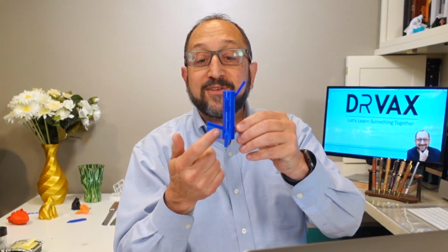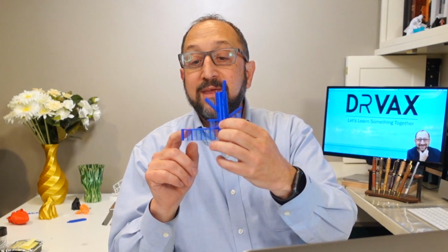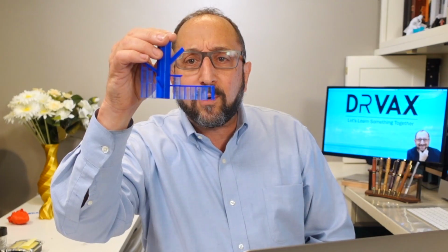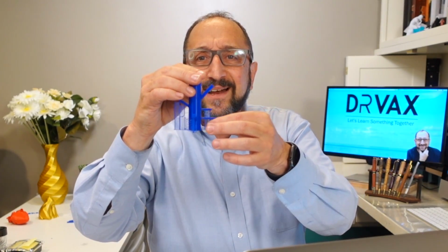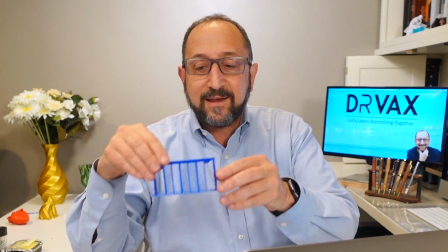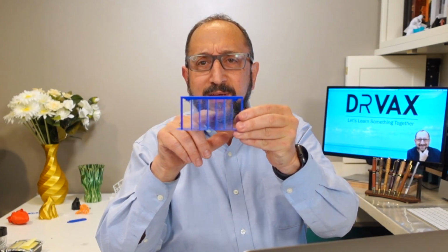This support is a solid support across here. These are individual supports. Now, if we look at these supports, it looks like they're connected together, but they're actually not. What's causing that feature? Here you can see the same thing here. What's causing that feature is that retraction is off when the slicer is configuring supports for the printer.